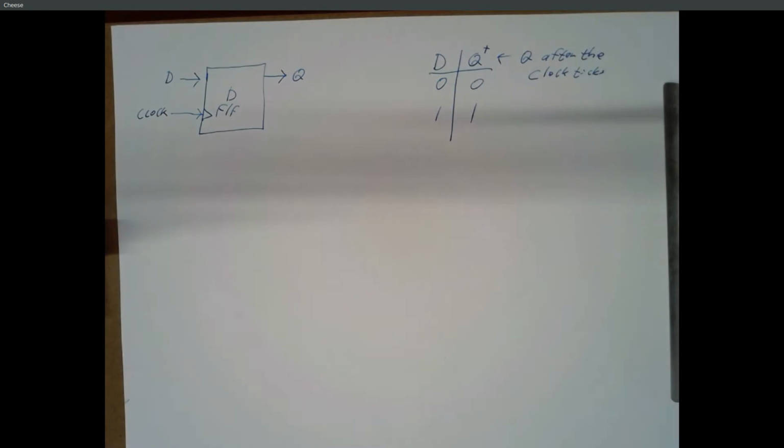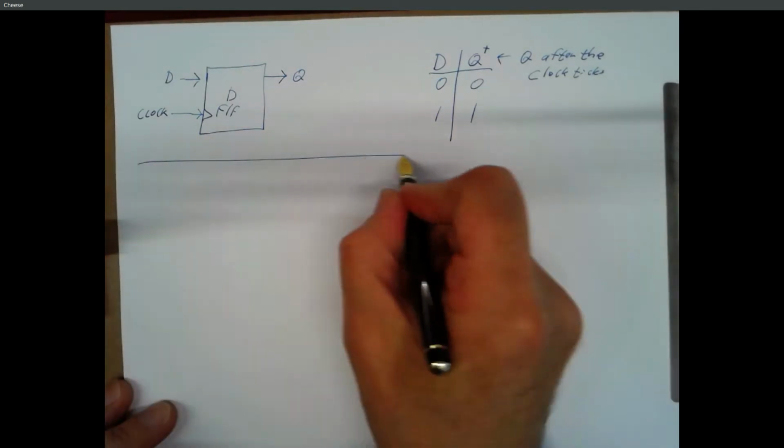Okay, so that's just a data flip-flop. It's useful for making things like registers where you have a whole bunch of numbers and you want to save them at some point in time. At that point in time, hit the flip-flop clock, all of those values get loaded in.